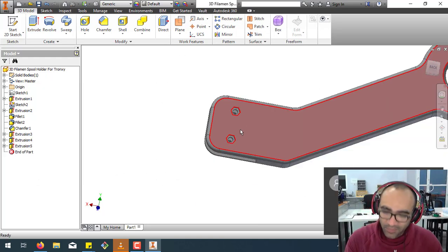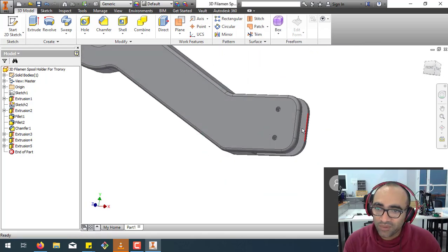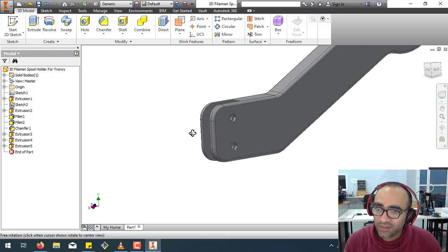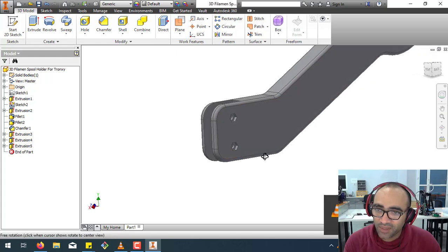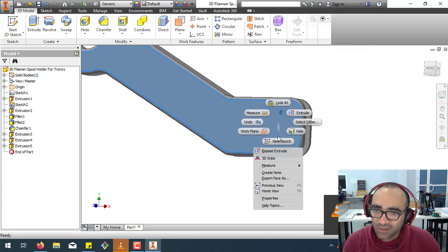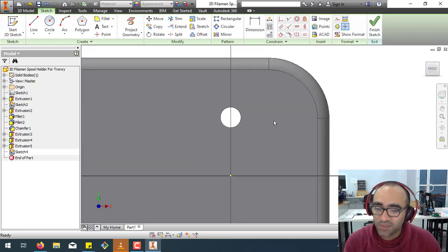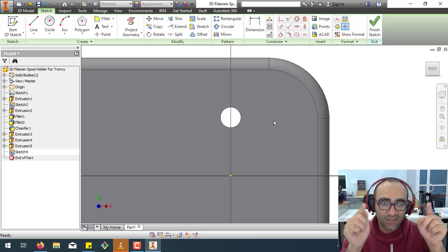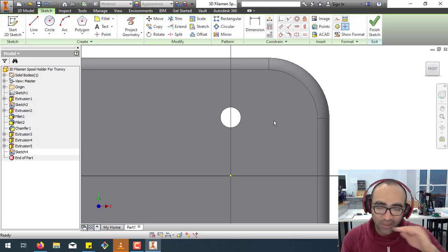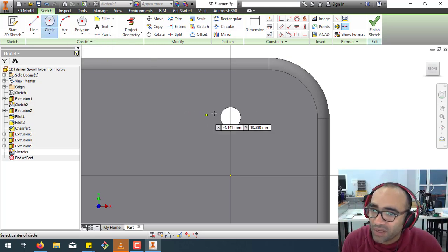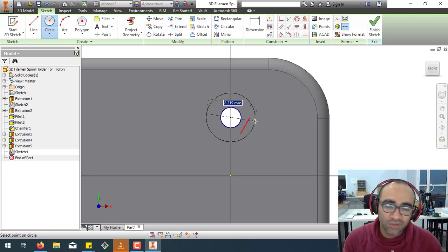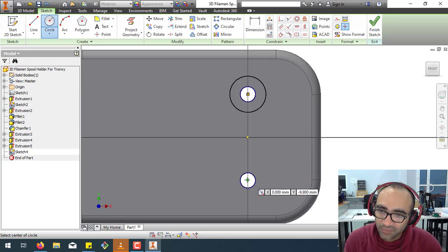Now it's ready. We put our screws over here, and then the nuts will hold this side. And now also even here, the screw head, especially if you don't have something like this in the screw head, I mean, it's not flat and then concaved. You have to make some kind of cutting over here so that it can flush the bolt along with the layer of the 3D printed part. And we equal them together,